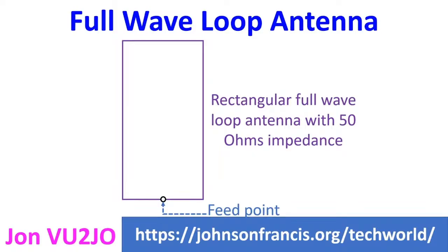A popular form of full wave loop antenna is quad antenna with a square shape constructed with a wire strung on an X-shaped supporting frame. Additional parasitic elements can be used as director and reflector. Such an antenna array will have unidirectional gain, which increases with each additional parasitic element, like a Yagi-Uda antenna. The antenna gets a diamond shape if mounted on a plus-shaped support.